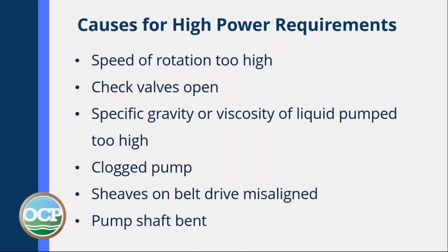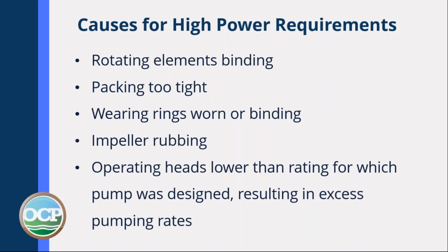Make sure the pump's not clogged. Make sure the sheaves on the belt are properly aligned. Check the pump shaft, it could be bent. You could have rotating elements in the pump binding against the housing. The packing could be too tight. The impeller could be rubbing the volute.